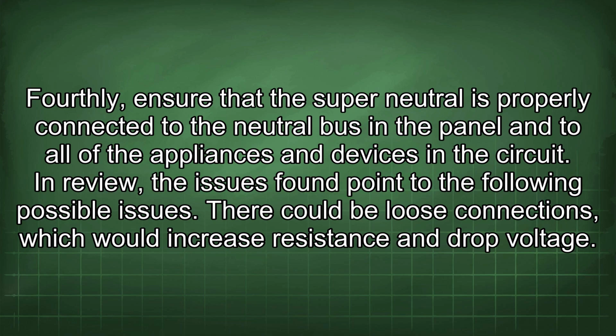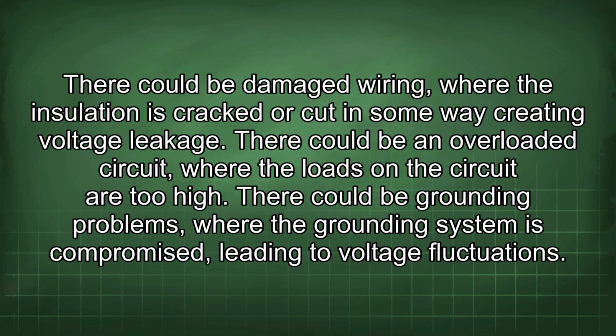In review, the issues found point to the following possible issues. There could be loose connections, which would increase resistance and drop voltage. There could be damaged wiring, where the insulation is cracked or cut in some way, creating voltage leakage. There could be an overloaded circuit, where the loads on the circuit are too high.